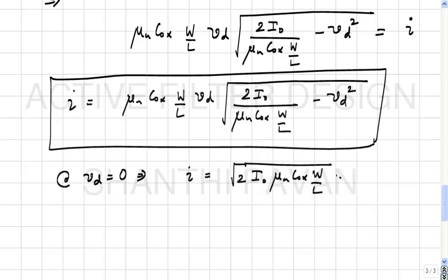Right? At Vd equal to 0, I will neglect this. Correct? And this will be square root, in which case this will be a constant. Then I multiply out the constant, the denominator cancels one factor, so you get this times Vd. Correct? Sure, at Vd equal to 0, I is 0, but around Vd equal to 0, what would you expect? The I to be linearly related to Vd, and sure enough it is. And what is that constant of proportionality? Gm of the transistor, which is carrying a current of I naught.